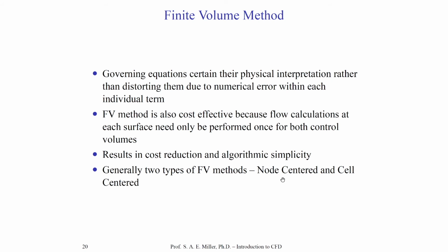And you should always know your solver if it's node-centered or cell-centered solutions. That way you know where your solutions are at. It's that simple. Let's now look at one finite volume approach, and we'll choose node center for now. We'll look at volume centered later.